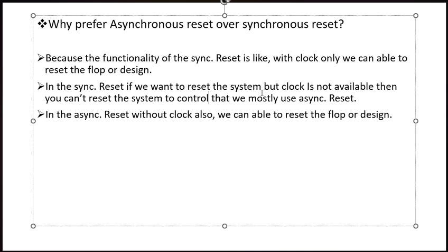But in an asynchronous reset we can reset the system without a clock also, because whenever we reset the system, it immediately affects the output of that system. That's why we prefer asynchronous reset over synchronous reset.